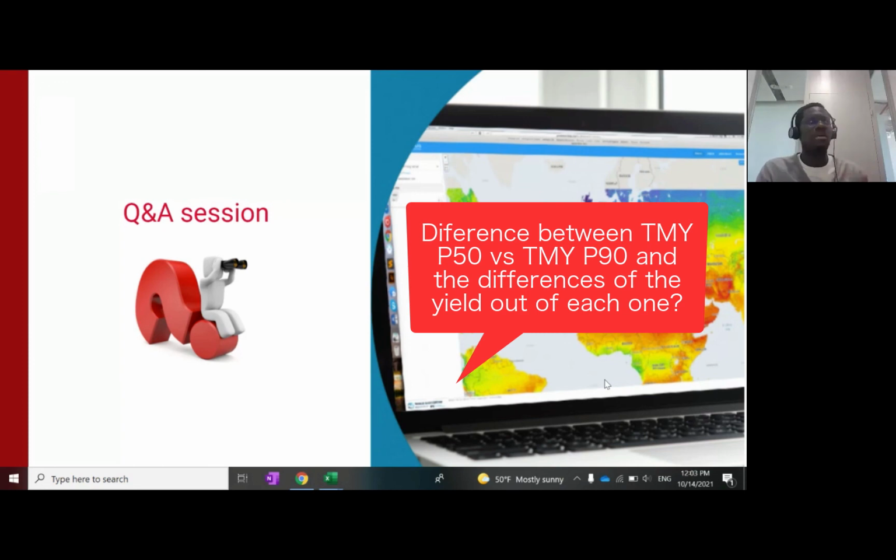To understand this a little more, we can look at the physical representation of the probability density, where we have the Gaussian curve against the energy. We talk about P50 when we have a 50% probability of occurrence, in terms of the solar resource or the energy yield which will be produced. However, P90 is much more conservative, more drastic, and usually for the financial aspect of a PV project, this is required by the bank. There, the probability of exceedance is much higher.